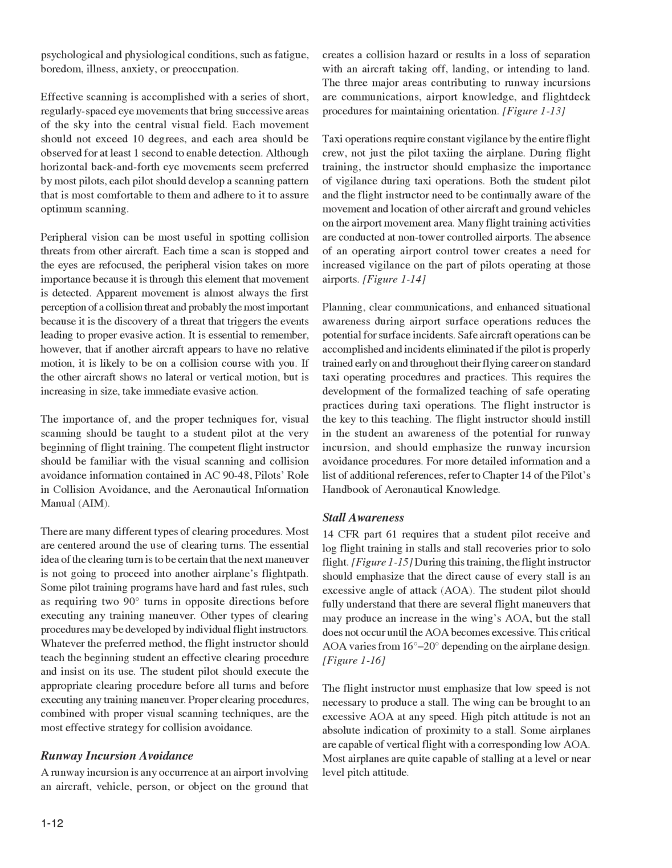It is essential to remember, however, that if another aircraft appears to have no relative motion, it is likely to be on a collision course with you. If the other aircraft shows no lateral or vertical motion, but is increasing in size, take immediate evasive action.